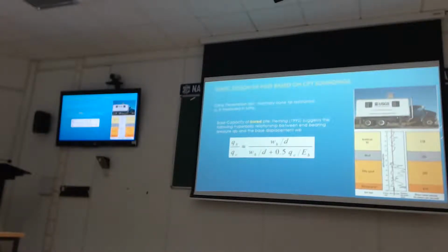So clearly, when you have fill, you got small QC. Where you're going through mud, you flatlined. There's no strength to the material. And when you got to silty sand, you picked up nicely, and dense sand, you're off the chart.